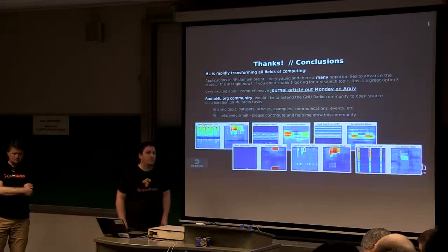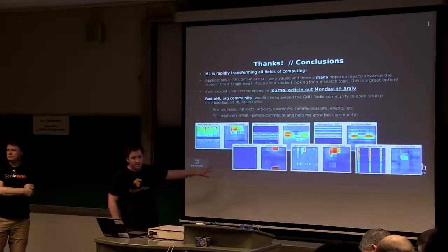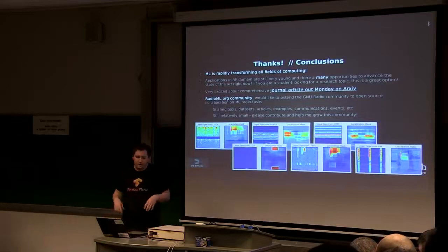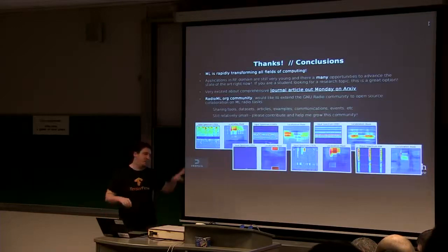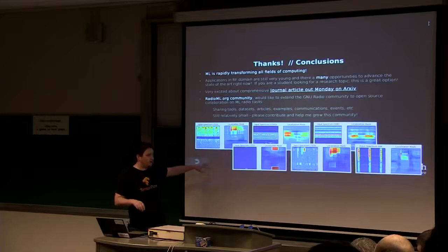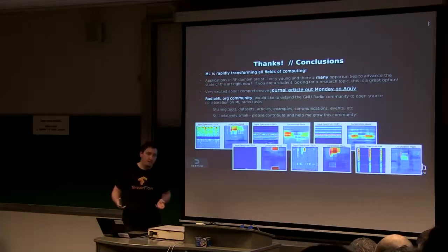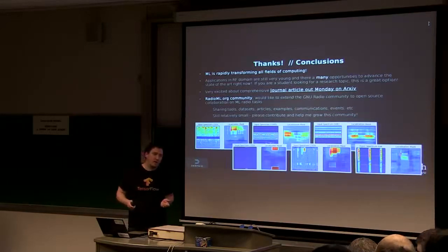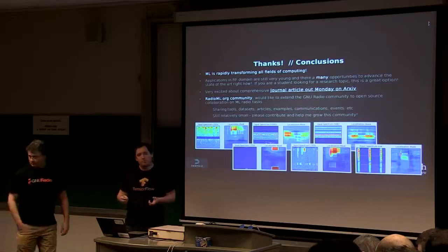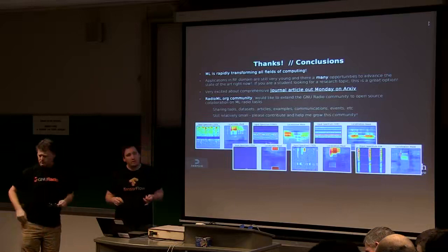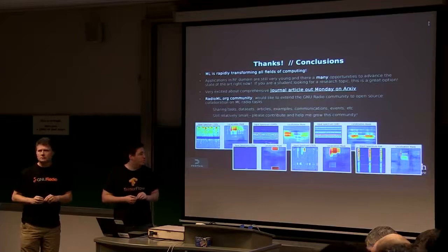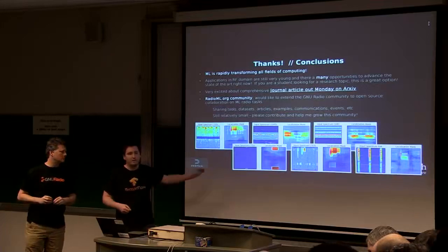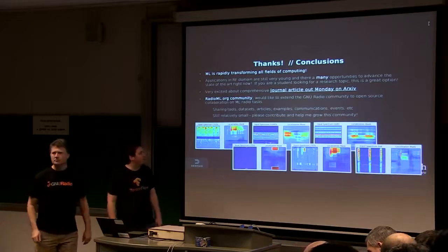Yeah, I can't do it justice here. If you read the paper on Monday, the question was about coding and whether we compared to Shannon. I didn't want to put everything that's going to be released Monday in here yet. But if you go through the paper coming out Monday, we have some very good baselines, where we're looking at comparisons to PSKs and DPSKs with the Hamming code, and we're basically right up against capacity. We're much more robust there in showing the capacity you can achieve with this, and you can come very, very close to the channel limit.